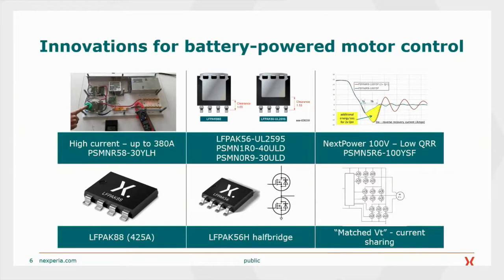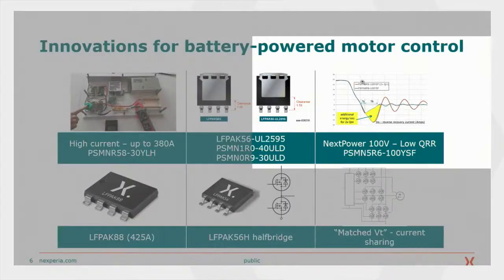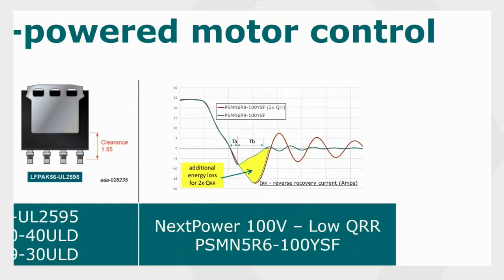So the softness factor refers to... I don't know if we can zoom in onto the top right corner picture, but there it shows the body diode characteristics. Yes, that's correct. The softness refers to how the diode, or the body diode of the MOSFET, recovers. The factor of 1 refers to the time TB over TA. The closer you get to 1, the better, the softer the recovery of the MOSFET, by reducing the ringing and the spikes, and that's what we aim for.